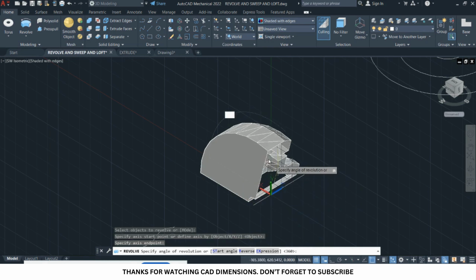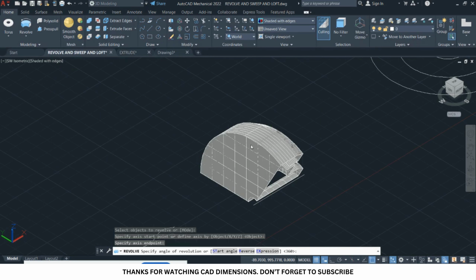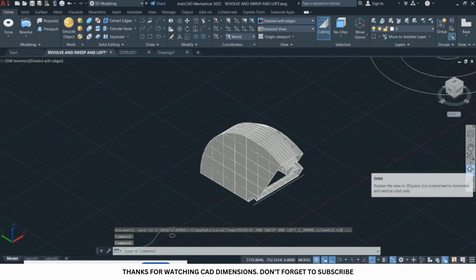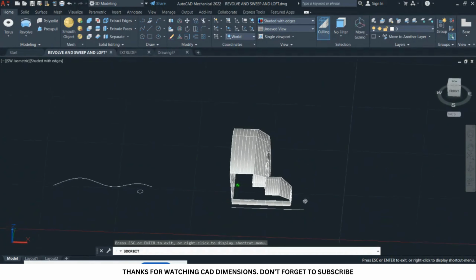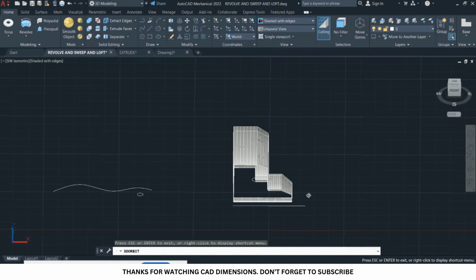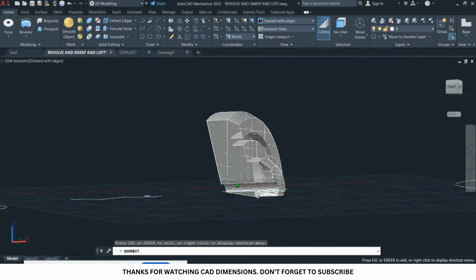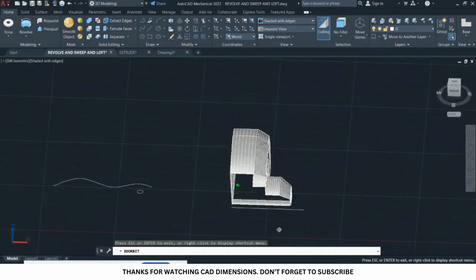Okay, and with respect to the revolve, you can revolve in 360, in 120, in any angle of your choice. So let me enter, let's say 120, right? So if I press 120, I'm able to create a revolve in that orientation. So you could see the revolve there. Now, if you realize, we've been able to create a revolve with respect to the edge. Okay, so you can also create a solid revolve.